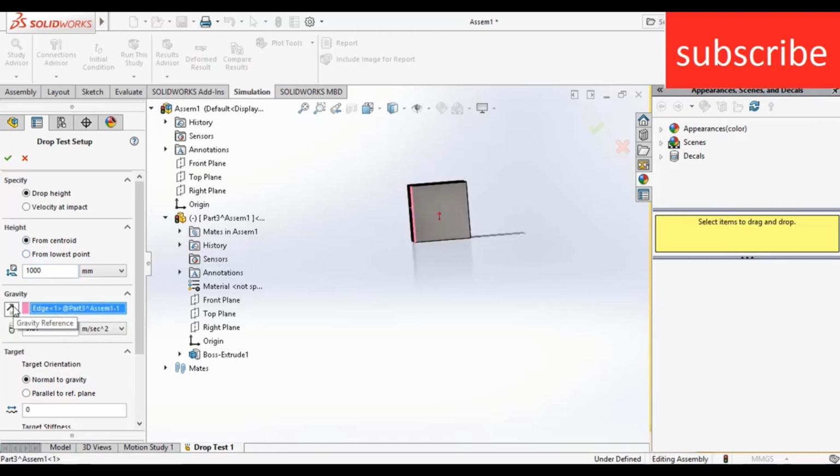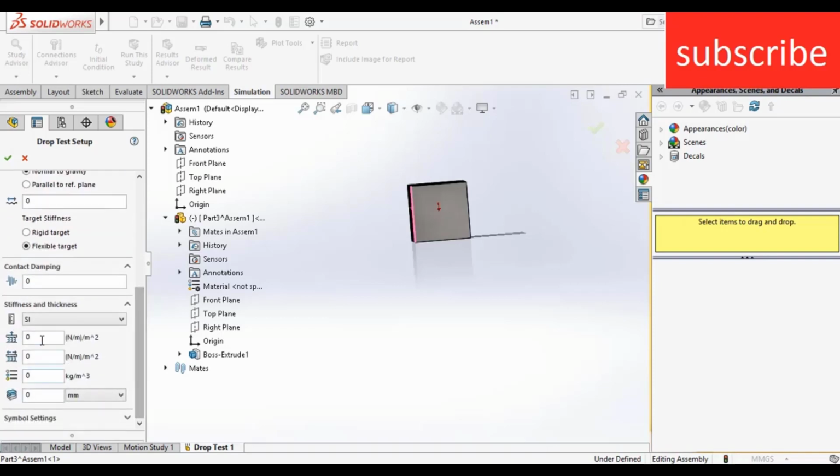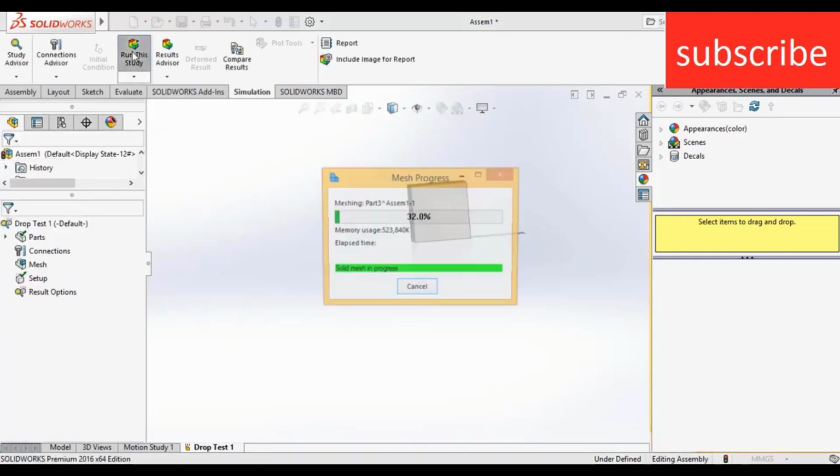Click here for reverse direction because gravity is acting downwards. And here you see options like normal to gravity, parallel to reference plane, rigid target, flexible target. Rigid target is one that doesn't deform on hitting the surface, and flexible target is one that deforms, and it asks for the stiffness and other things. So in this study I'm going to use rigid target. Okay, so click OK and click on run this study.